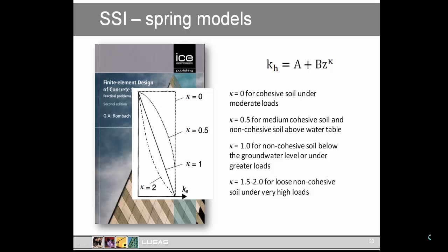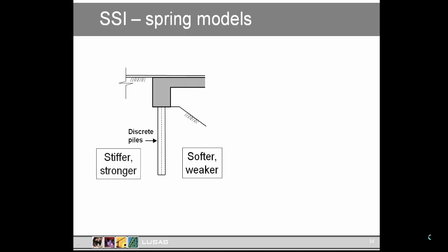We also need to take account of the slope. Because of the front slope, the stiffness and strength of the soil, as represented by any spring or nonlinear joint, ought not to be as substantial as that attributed to the soil behind the abutment. Added to that, the remoulding of soil over many thermal cycles should be taken into account.